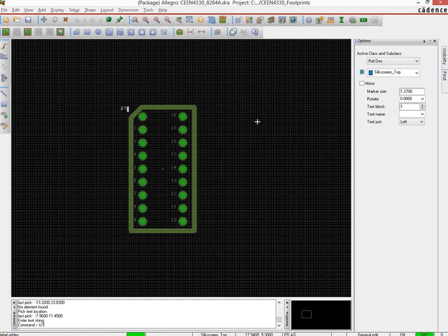That question mark gets replaced by the component number on your board. So if you have 3 components, the question mark would be updated to U1, U2, U3 when finally the board is designed. Now these are those little designators which you see on a PCB board, the numbers of the particular components. So that is the one that you would be able to see. So that is the silkscreen.